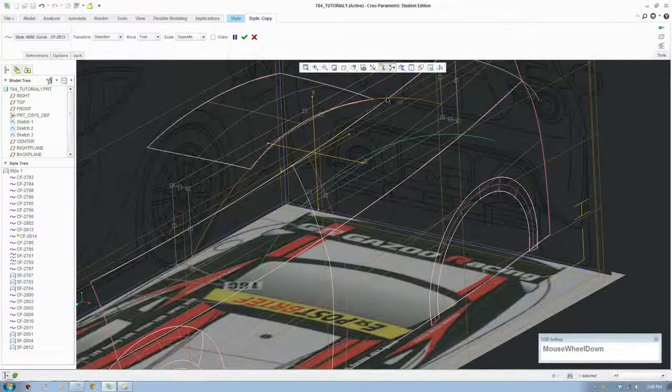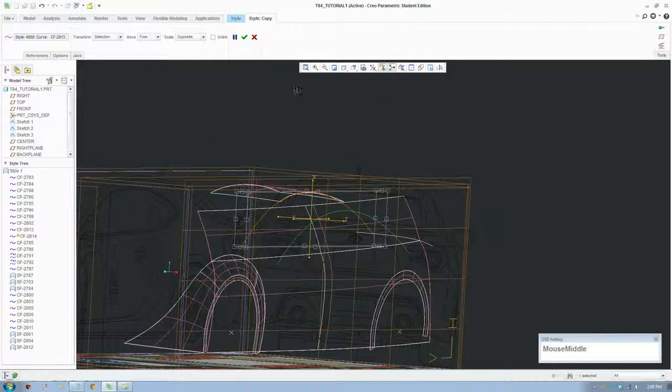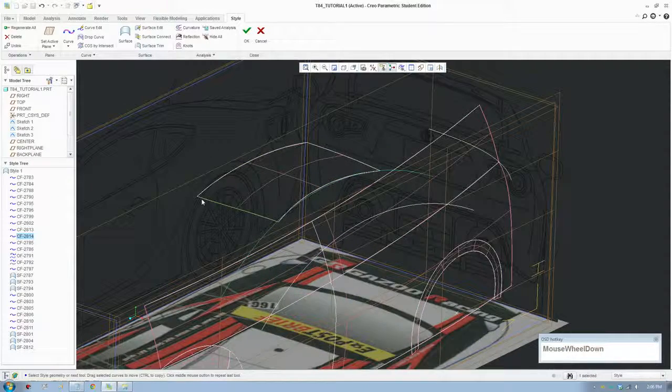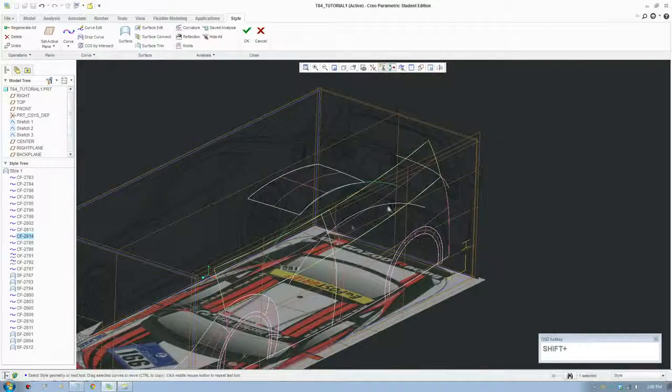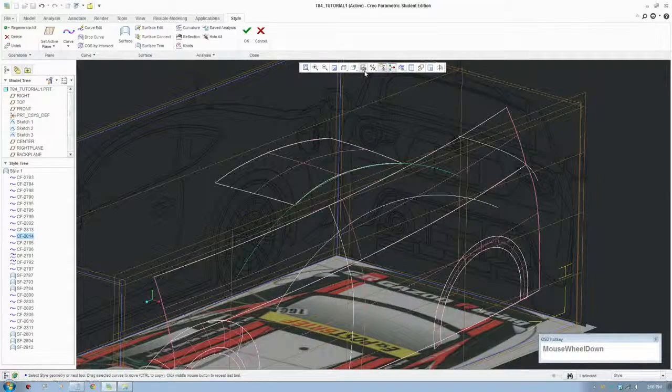The reason I made a long curve here and a long curve here, because when you make a surface, both of the curved surfaces need to be a similar length, because if it's too small, it's gonna shrink in and the wireframe won't look well, and it's just not a good idea. So the key is keep your surface even, keep the length the same, make sure the surface is nice and simple.